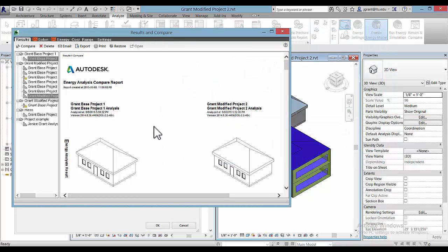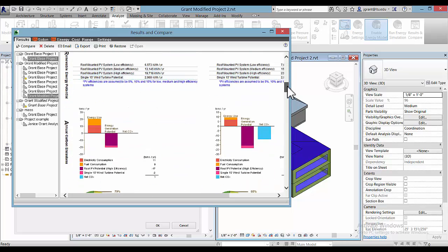and then open another project of your own, whether it is the first project that we worked with in this course or one that you've worked with in a different class, and change the energy settings so that you can establish a location and some of the settings that we used, and then run the energy simulation and export it as a PDF so that you can submit both the compared report and the new one that you'll create with a somewhat bigger model with additional spaces. They will all be different and have different results.